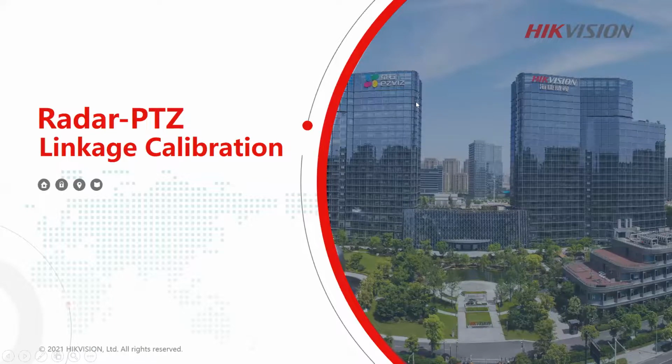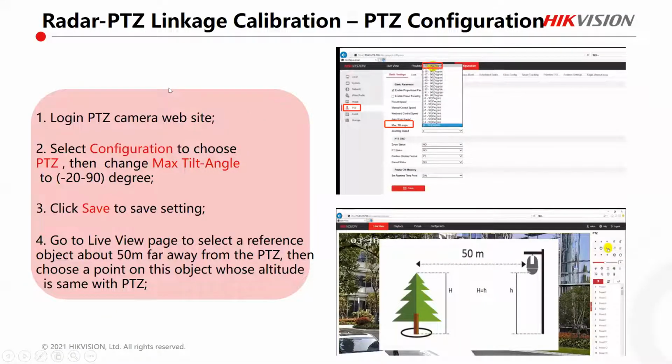All right. So just to go through the linkage itself, first of all, obviously, you need to log into the camera. That will help. So you need to log into the PTZ. Once you've logged into the PTZ, very importantly, will be this section here. Can you guys see it with the mouse? Let me do this because I have to hammer on this section. This part is very important, right? Reason being, you need to make sure that it's set at -20 to -90 degree angle. You need to have that degree angle. If you don't have that degree angle set on your PTZ, you are looking for trouble. Keep that in mind. Obviously, make sure that you save it. Some guys go and click on it and they don't save.